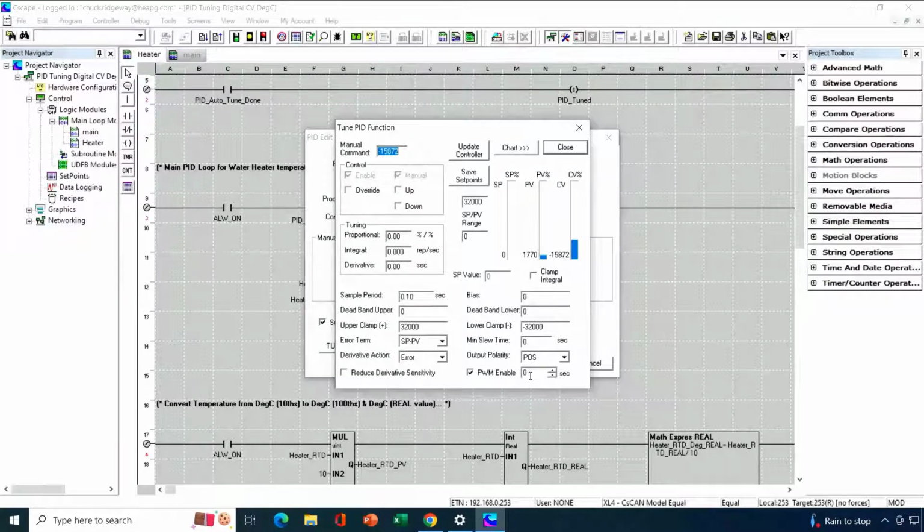And I'm setting the cycle time at 0 because, again, I'm not concerned about cycles that happen frequently on my solid state relay. No issues there. Now, even though the output is an on or an off, the OCS PID loop is still doing an integer-based CV calculation. If the value of the CV is below 0, then my digital output will be off. If the CV calculation results in a 0 or higher, then my output will be on. So that's what will be happening.